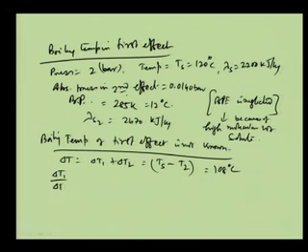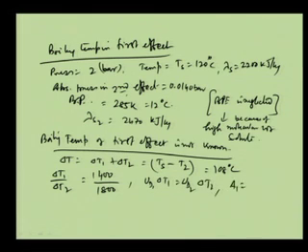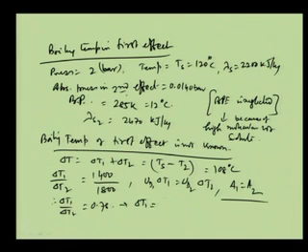Then from here, delta T1 by delta T2 is also 1400 by 1800, based on UD1 delta T1 equal to UD2 delta T2, with A1 equal to A2 from this relationship. So, we have delta T1 by delta T2 equal to 0.78 or something like that, and then from here we find delta T1 is equal to 47 degree centigrade, and delta T2 is equal to 61 degree centigrade.